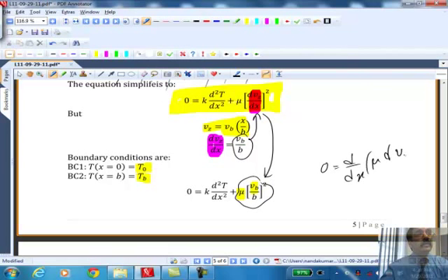That is the momentum equation for a case where you still have a Couette flow, one-dimensional flow, but mu is a function of temperature. You can integrate this once, but the second integration is going to be difficult because you don't know what temperature is. So you would call that a fully coupled problem where each variable affects the other. The two equations must be solved simultaneously.